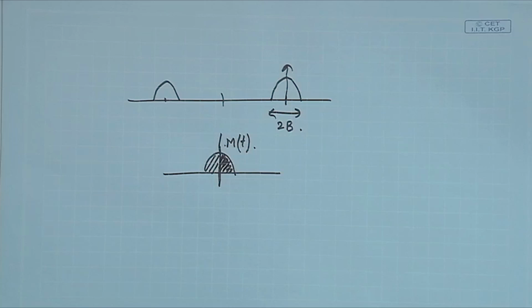I can always get back my signal, we will discuss that later on, through the positive half only, or just one half, either positive or negative, whichever half you require. From that portion only I can extract the whole signal. That is possible, we will show that that is possible. So, if we can employ something where we do not have to transmit both the bands, then I can save some bandwidth, because this is the band it will be occupying in the channel. So, 2B is lost.